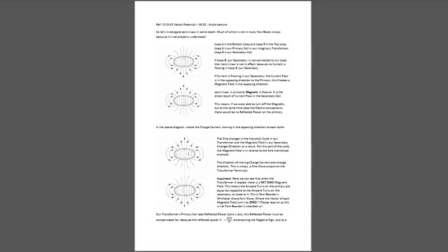So let's investigate Lenz's law in some depth, much of which is not in many textbooks simply because it's not properly understood. Loop A is the bottom loop and loop B is the top loop. Loop A is our primary coil in our imaginary transformer. Loop B is our secondary coil. If loop B, our secondary, is not connected to our load, then Lenz's law is not in effect, because no current is flowing in loop B, our secondary.